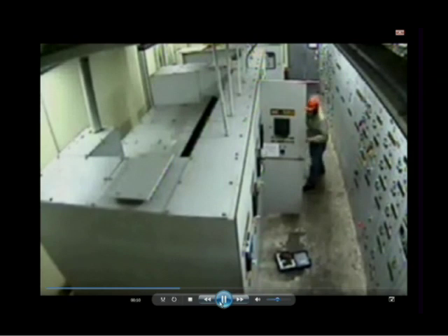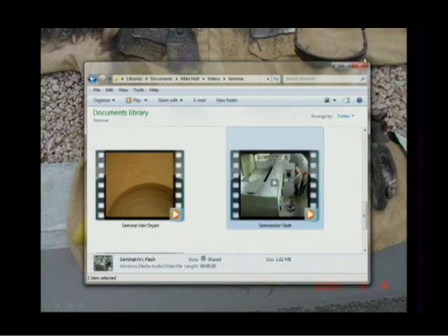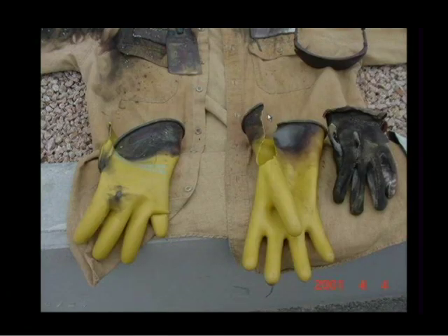Yeah, he's ratcheting it in to where it's on wheels, and then a thread pulls the breaker in and engages the contacts. This is half speed. Now, he doesn't expect his life to be changing forever at this moment. That's real time. That's how long this blast is taking place. Mike, this is also a good reason why a lot of the breakers now are being remotely racked. You put up equipment to the breaker and have an umbilical cord. When you press the button, you can stand away from it, and the equipment in front of the breaker racks the breaker in. Oh, nice.